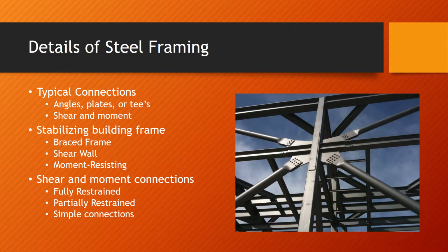Shear connections and moment connections. The American Institute of Steel Construction identifies three types of beam-to-column connection. Fully restrained: under normal loading, angles between members will not change. Partially restrained are not as rigid as fully restrained, but are dependable and predictable. Simple connections or shear connections are unable to resist rotation and have negligible moment resisting capacity. These frames must be supported with diagonal bracing or shear walls.